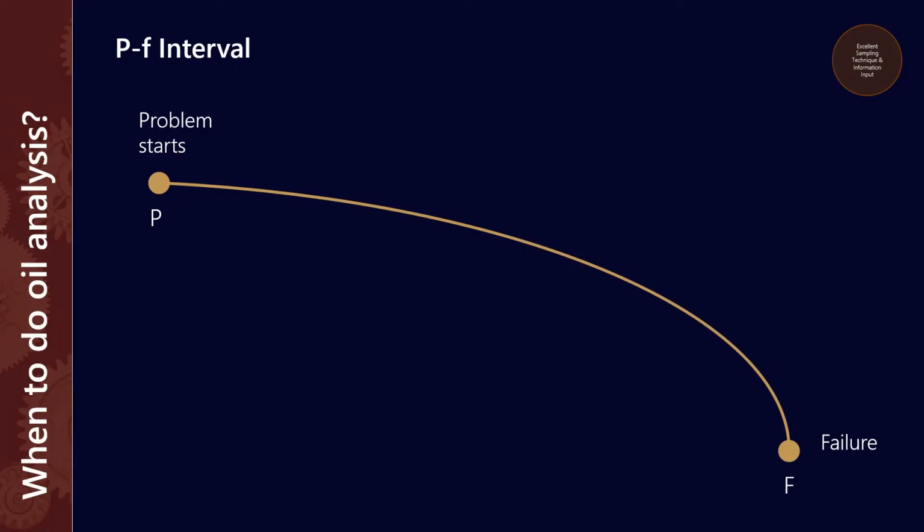As an example, I use the example of a bearing failure. If the bearing failed catastrophically, it started with some kind of event in the past. Maybe when the bearing was installed, it was installed with a slight misalignment. Maybe it's actually the wrong bearing size or wrong bearing fit. Maybe there were some contaminants introduced into the bearing. Whatever it was, the problem started a very long time ago, and it didn't manifest itself for a while.